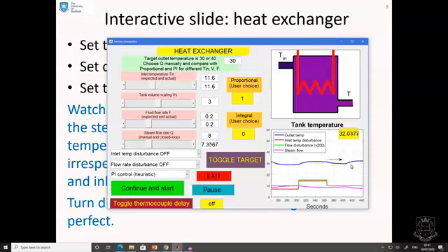But notice the PI is going to bring the temperature back about as fast as you reasonably could, given the size of this tank and the like. We could also change the fluid flow rate. And again, you see how the steam flow has been changed automatically by the PI, and it's bringing the temperature back. And that's really about as quick as a human could do it, if not maybe quicker.